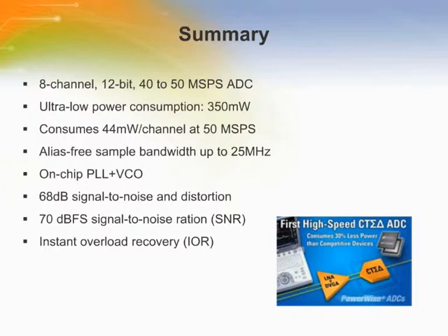To fully exploit these considerable benefits of the CT sigma delta technology, the ADC 12EU050 also includes an on-chip clock conditioner that eliminates the need for high-performance, expensive clocks. Finally, the ADC 12EU050 avoids the hazards of input overload presented in sigma delta analog-to-digital converters by offering a means for recovering immediately from an input overload event.